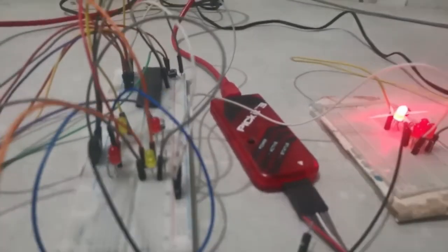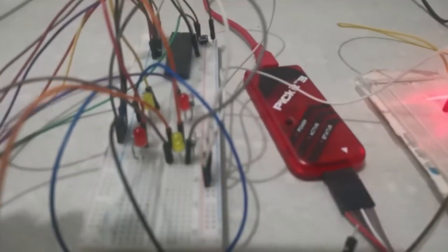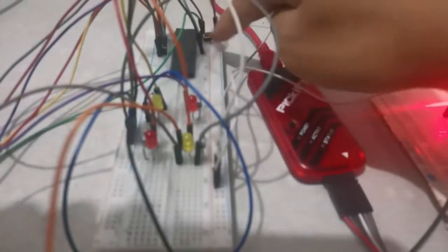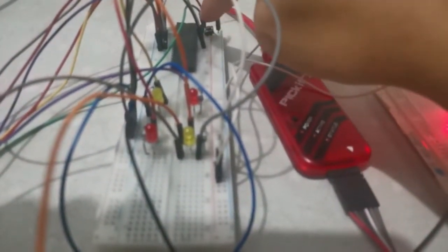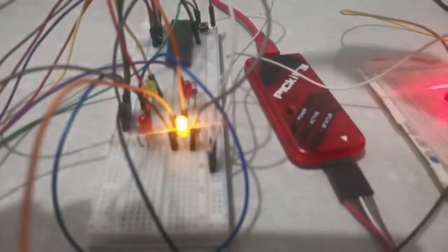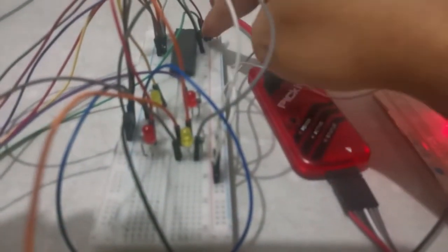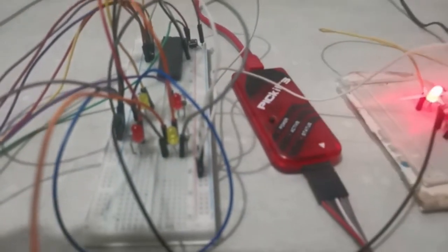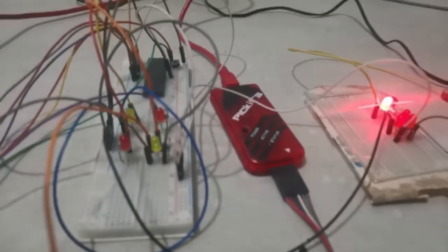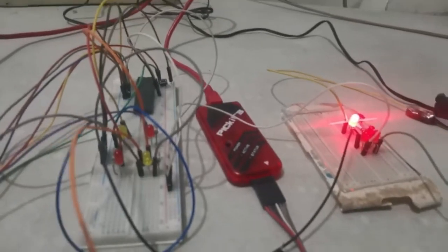Okay, so here is the network. We've programmed the D2 LED as RA4, meaning it is the fourth quadrant LED here. So if I press from the off state, theoretically it should turn on because the switch has changed state. It turned on. If I press it again, it will turn off. And on again, and off again. So our code is a success. Moving on to the next part of the experiment.